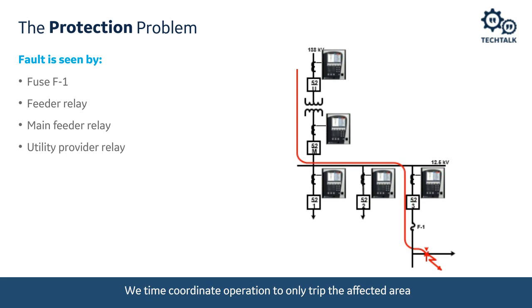So as we stack up these time overcurrent elements, we create more of a time delay, which is not necessarily good. That creates arc flash incident energy issues that we may have to deal with. It also means that the fault is going to be there longer than we might want it to. But nonetheless, that's what we're going to do with time overcurrent protection.